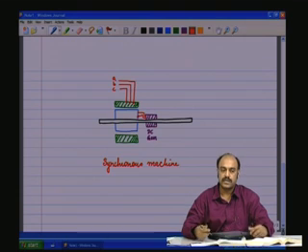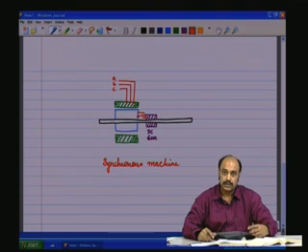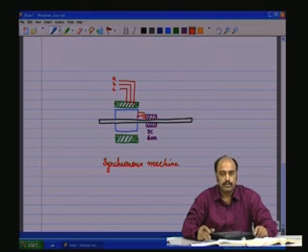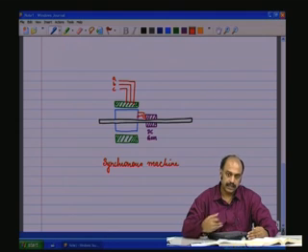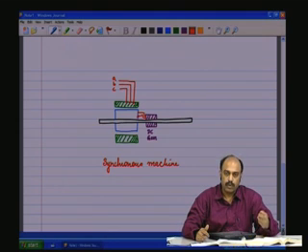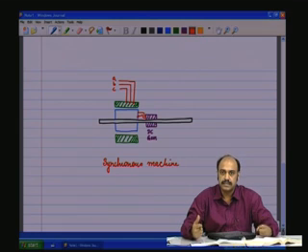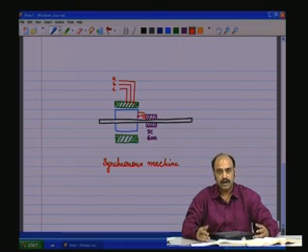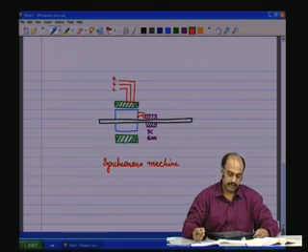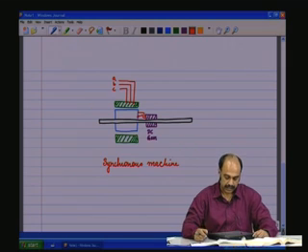So the rotor also has squirrel cage bars, and they are used for starting up the synchronous motor, bringing it close to synchronism, and then the DC generator provides the excitation which magnetizes the rotor and makes the rotor lock on to the rotating magnetic field. From there on, the rotor rotates in synchronism with the rotating magnetic field.